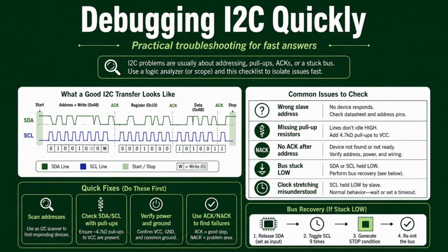Also check for clock stretching and configure a reasonable timeout instead of assuming every low clock period is a fault.